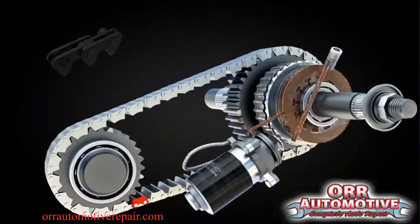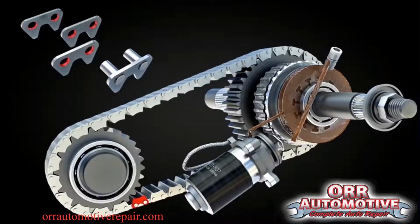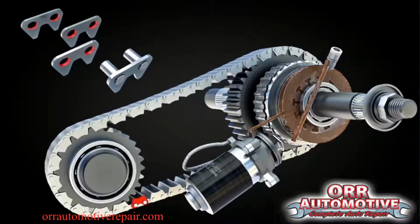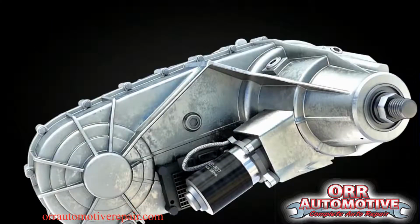The transfer case uses a high-strength chain to transmit power from the engine to the front differential. Chains can become damaged as a result of harsh gear engagement or low fluid level inside the transfer case. Worn or damaged chains can cause further damage to the transfer case gears. Correct fluid level and quality can reduce the risk of chain damage.